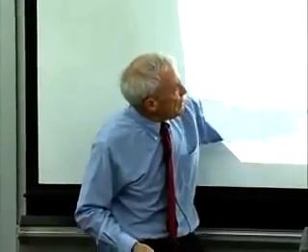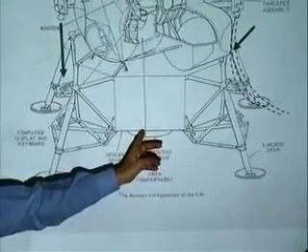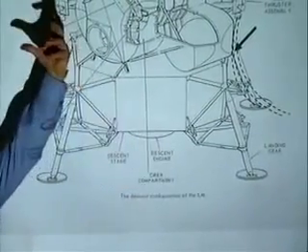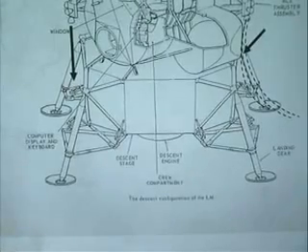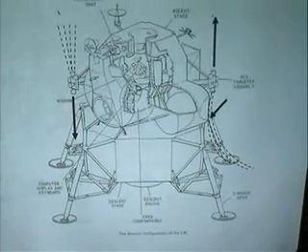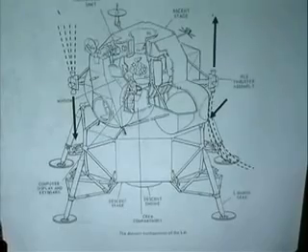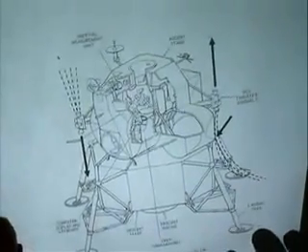So I said, well, maybe that 0.2 of a degree per second gimbaling rate is fast enough to control the big configuration. And one motivation for wanting to do it was that the control authority of these little jets over the big configuration wasn't going to be that great, and a lot of propellant was going to be expended, so what could be done?